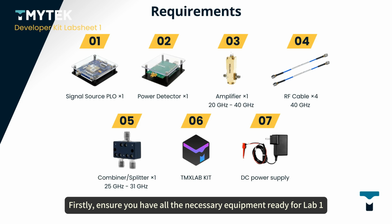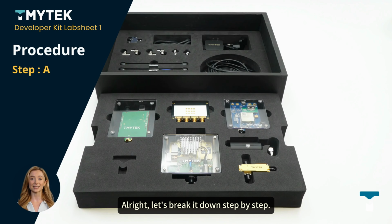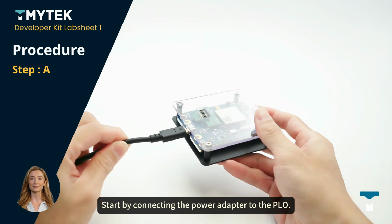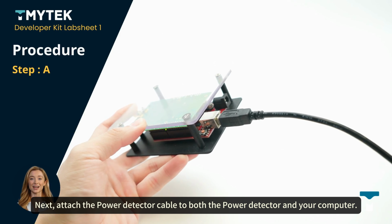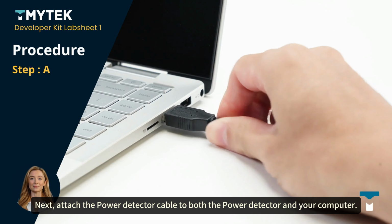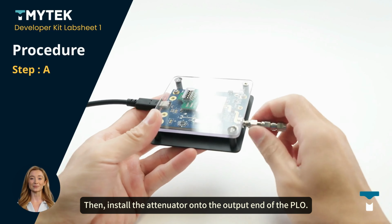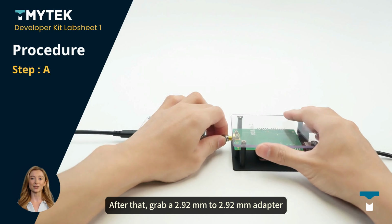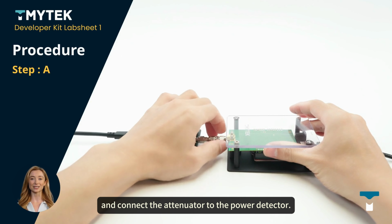Firstly, ensure you have all the necessary equipment ready for Lab 1 as per the course instructions. Alright, let's break it down step by step. Start by connecting the power adapter to the PLO. Next, attach the power detector cable to both the power detector and your computer. Then, install the attenuator onto the output end of the PLO. After that, grab a 2.92mm to 2.92mm adapter and connect the attenuator to the power detector.